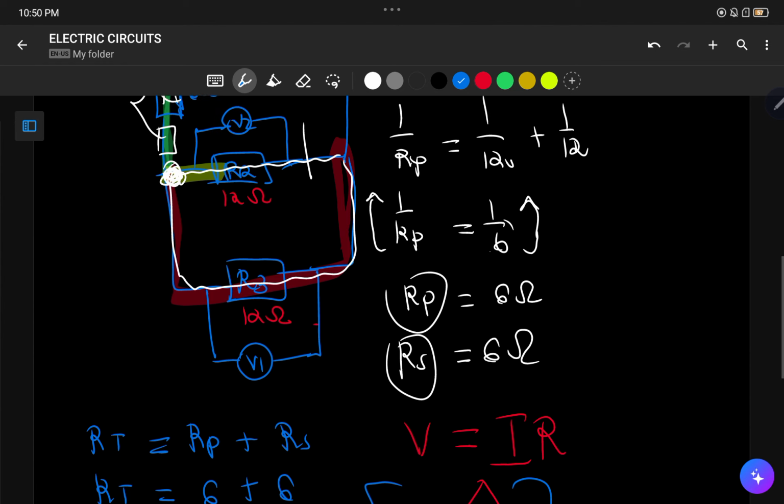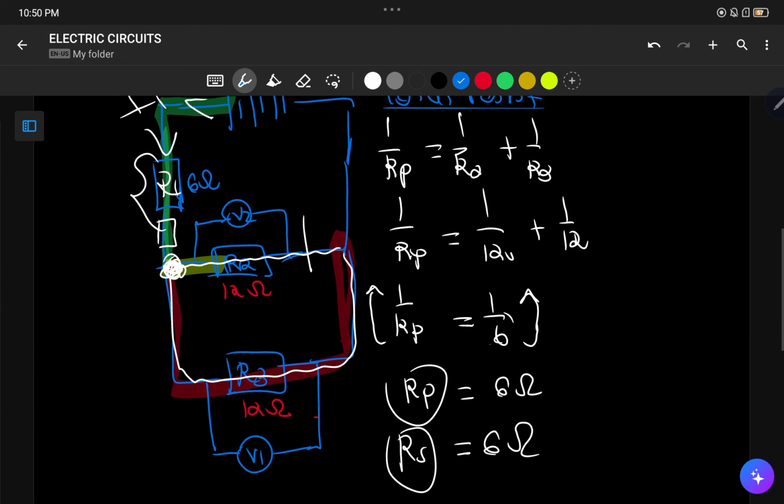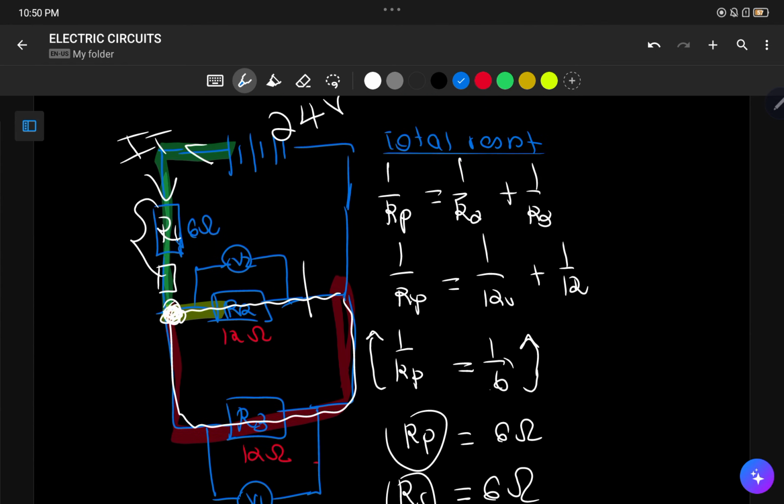But by the look of things in your illustration, you can see that current in resistors that are in series to one another does not split. That means that a current of 2 amperes would flow from the positive terminal of the battery and pass through R1, because R1 is in series, and in series current does not split.